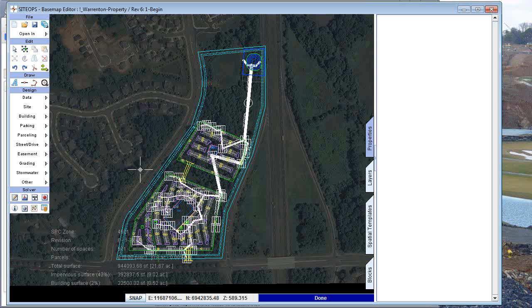design. Okay? So at that point, different counties have different regulations, and you would then go to your normal pipe design and pond design criteria for that county. But the good news is if you can use a rational method to get this far with the pond sizing and the pipe sizing, then your normal county methods will also work. The rational method is a very conservative method, and so this is like the worst case scenario. And if you go to final design, you can improve this with your local county regs, and you should have no problems if you can do it at the rational level.